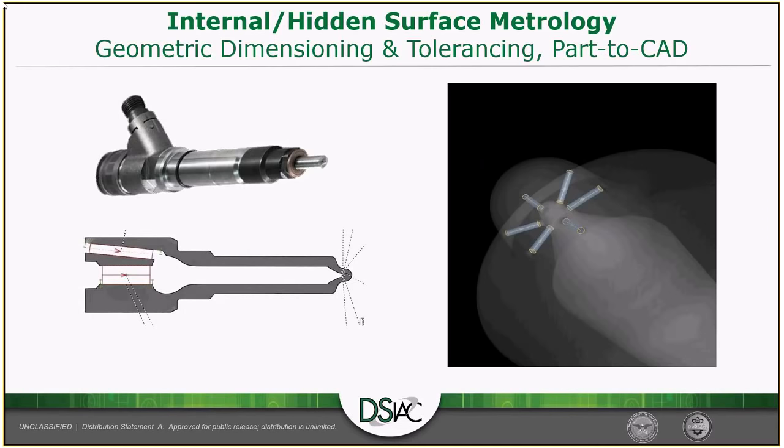And then now we'll get into some of the metrology, and like I said, this is kind of a forefront for CT now, is starting to get this accepted as a metrology tool. So I'll show you some of the examples here. This is an injector, and you can see those tiny chambers and orifices in there. We can measure the diameter and the consistency of the diameter, and you can go in, as you would think, with a CMM using a physical touch probe.